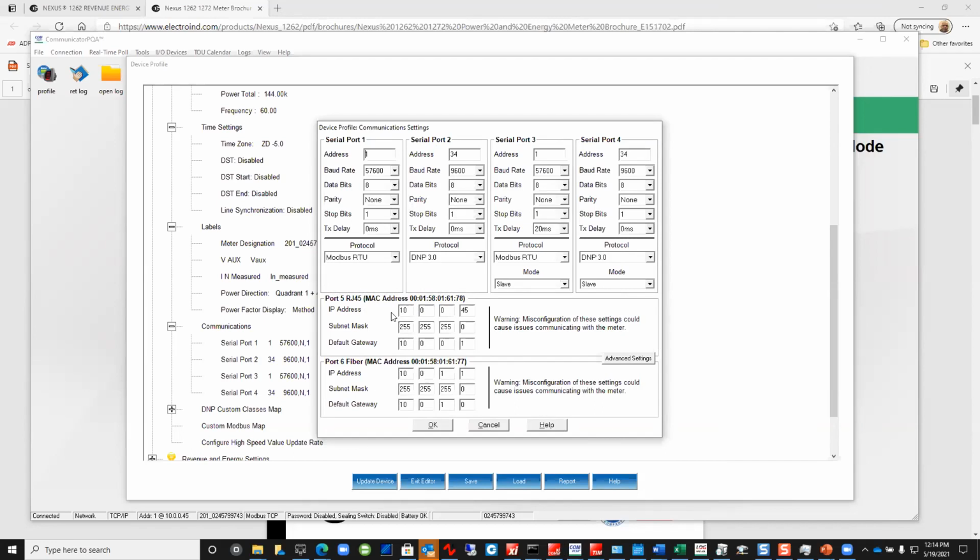These are electrically isolated ports, so you can have two network connections. And here is where you put your modules or your display outputs. You can set your addressing and so on. Again, for port 2, we're getting DNP 3.0, so that your SCADA folks are getting that. Here could be something else: either you are hooked up to a display, or you could be reading that over Modbus RTU and so on.